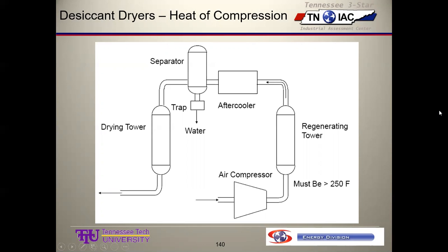And then you put that air, and that air is full of moisture. It hasn't dried a bit. That's all the moisture that came into the compressor still in that air. And you put that into the regen tower. And if it's hot enough, it can still strip the moisture out of the saturated tower. So then coming out of that regen tower, oh my goodness, you have moisture on top of moisture. You've got all the moisture that went in the compressor, all the moisture that got stripped out of the regen tower, and then we go into the aftercooler.